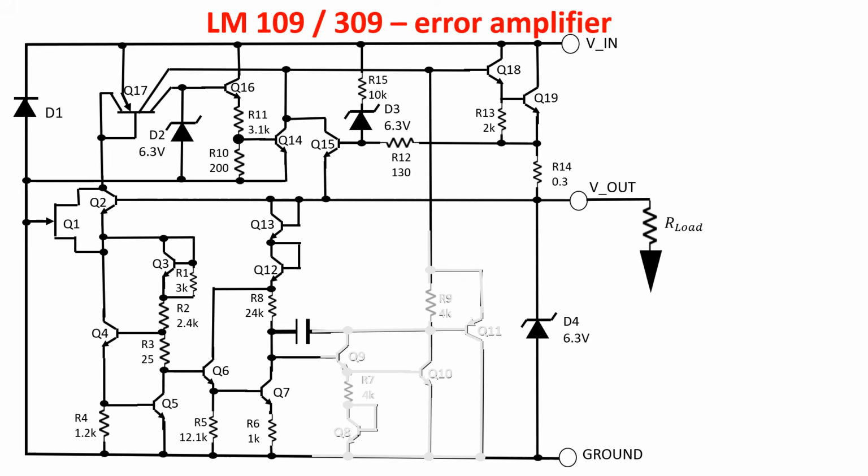The error amplifier has one more feature. You see on R7 we have a PTAT voltage given by the difference of the base emitter junctions of Q10 and Q8. So when the temperature raises, the collector current of Q9 raises as well, drawing current from the pass transistor. This behavior compensates the increasing current in the pass transistor due to the temperature increase.